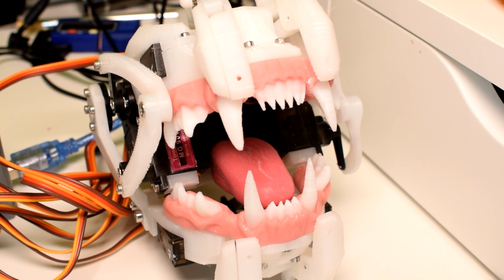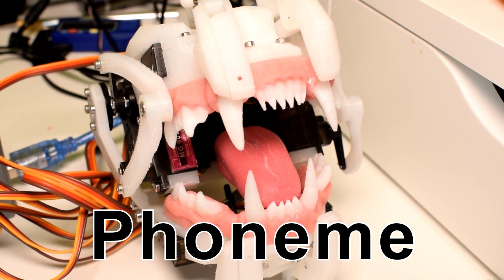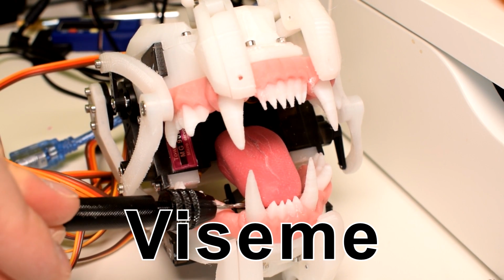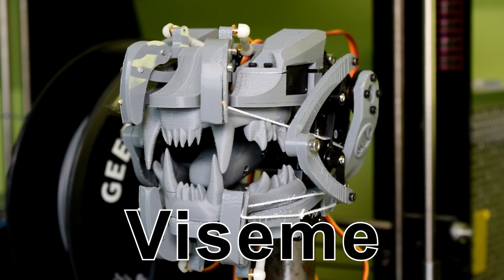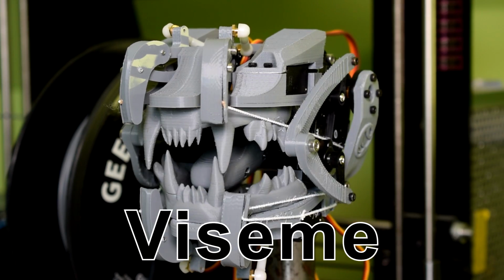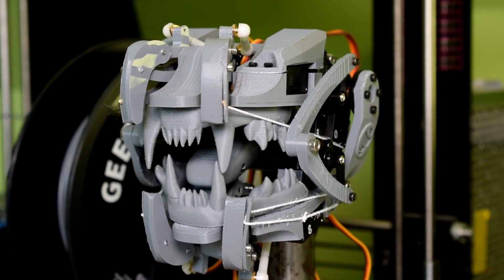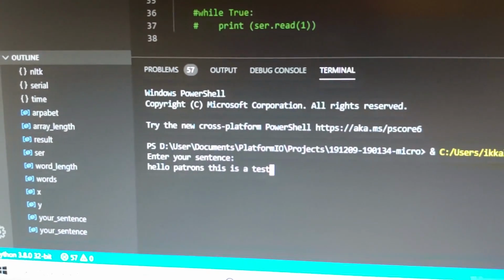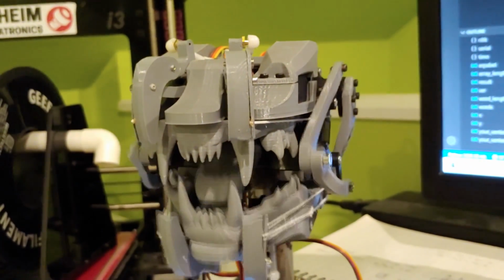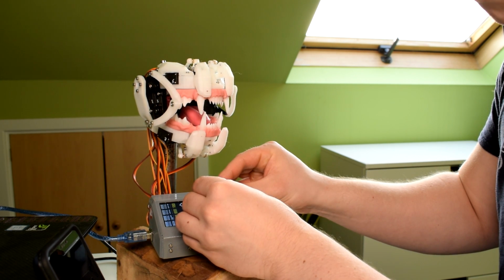So in speech, you can describe a phoneme as a unit of sound that makes up a word. A viseme, on the other hand, is the way the mouth looks when certain phonemes are being made. So you could describe it as a mouth position when a certain noise is coming out of your mouth. The control methods that I've used so far focus on finding a phonetic translation of a sentence and then translating this into a sequence of phonemes, which are then sent to the animatronic mouth and expressed as a sequence of mouth poses or visemes.